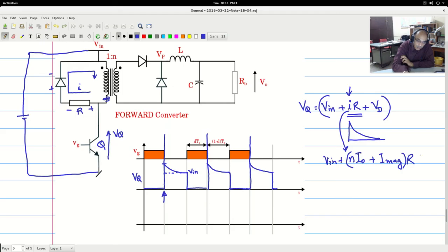Vn plus Vd should be less than the VCEO rating of the transistor or the MOSFET. So based on this, you know this by design, this by design, this by design, this can be the datasheet value chosen of the chosen device. Knowing all this, this can be estimated. This is one condition.